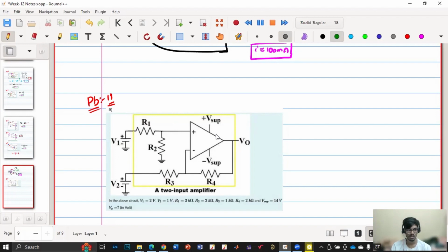It is a bit oscillating. The input step itself is not proper because the function generator has a minimum current requirement. Whereas if you take some other equipment which has enough driving capability and provides enough output current, then the step function will be proper. But with the equipment that we have in our lab, this is creating that issue.